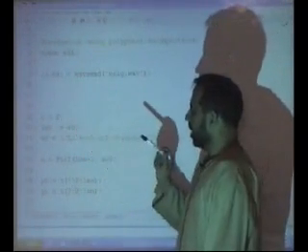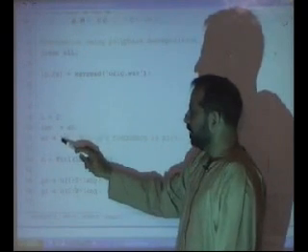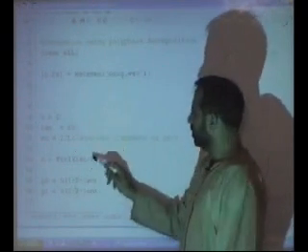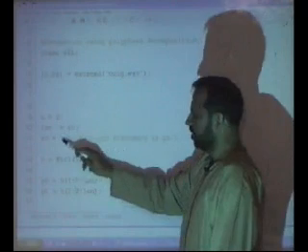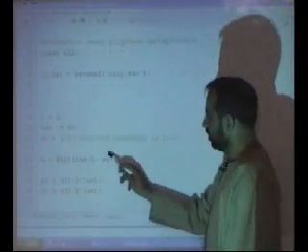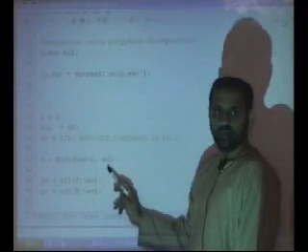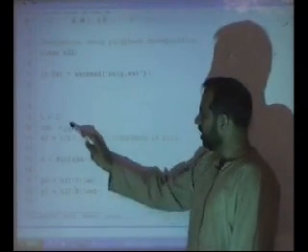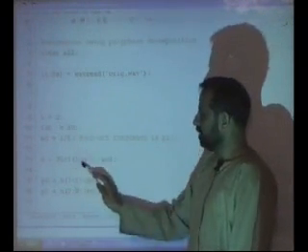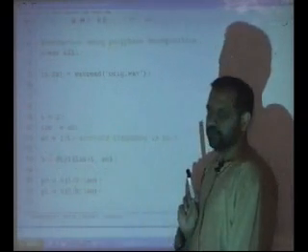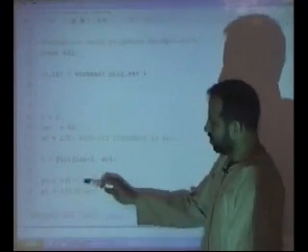Let's say I want to design a filter in MATLAB. Pi is omitted, it's a normalized axis. So once you say pi over L, you only say 1 over L, 1 over M. So this is the cutoff frequency of the decimation filter, pi over 2 filter. So I design a length 40 filter using the FIR1 command. This is H. Now this is the polyphase decomposition.